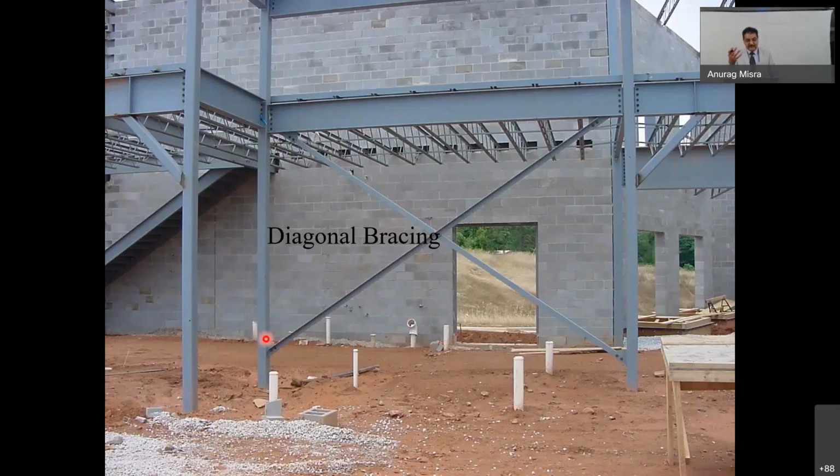Normally designers provide some kind of shear walls, or the lift wells are placed in a way that they are able to handle most of the horizontal forces coming onto the structures. But otherwise, the bracing is a very common practice in these steel multi-story buildings.